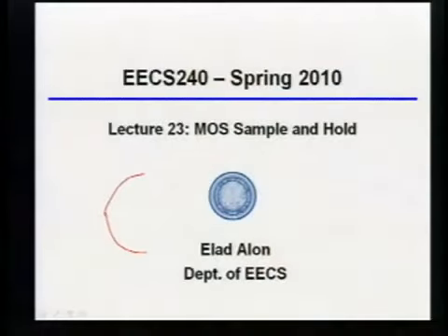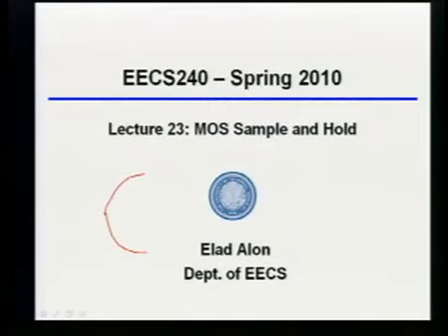So let me maybe specify it this way. Basically, your outputs have to essentially be quote-unquote stable by the time you clock them. Let's maybe even make it a relative spec. Let's say your output swing should be at least 200 millivolts at the output of the comparator, which I think is about what I gave you, approximately speaking. That one has to settle to within, let's say, 2 millivolts in order for me to call it a good digital level. Probably a little bit too mean, but just to make sure that nobody tries to abuse anything. Does that make sense?